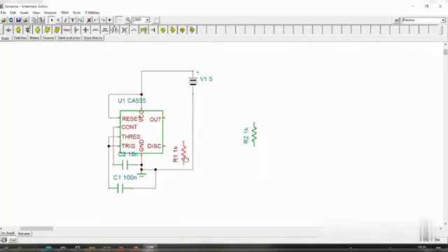So here I am clicking here because this is to be connected like this, not to the output, but these 2 points are to be connected here, that is connected to the discharge pin like this. And the other end should be connected to the positive supply plus 5 volt, and this should be connected to this capacitor, that is, this will form the RC time constant of the monostable. So here you can have it like this, and connect it to this capacitor.